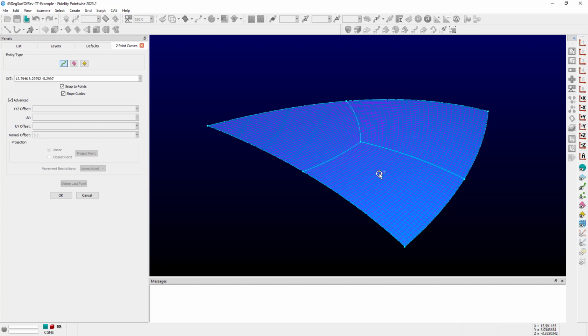You can see as I mouse over these domains that already exist, these are structured domains, that all of the interior points of the domains are pickable locations indicated by the bullseye cursor that you see around the mouse. In order to avoid accidentally selecting any of those interior points, which can be easier to do when there's quite a refined clustering in your surface grids, I'm going to turn off the display of those domains temporarily so that I don't accidentally pick any of those points.